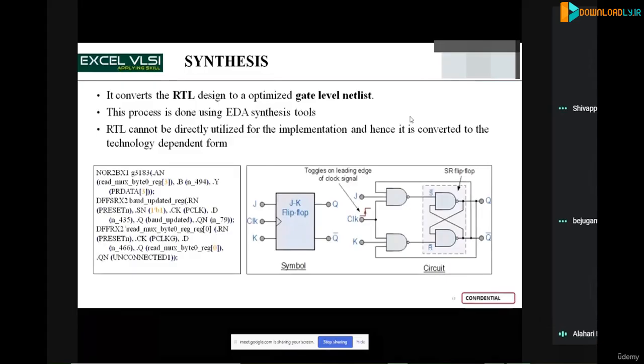Yes, but after opening the file only can we understand that. Yes, the content. Otherwise, both files will have a top level module. Inside the module, what will be in the netlist file is the top level module inputs, outputs, and the netlist within the content, and in the other one, the Verilog syntax.